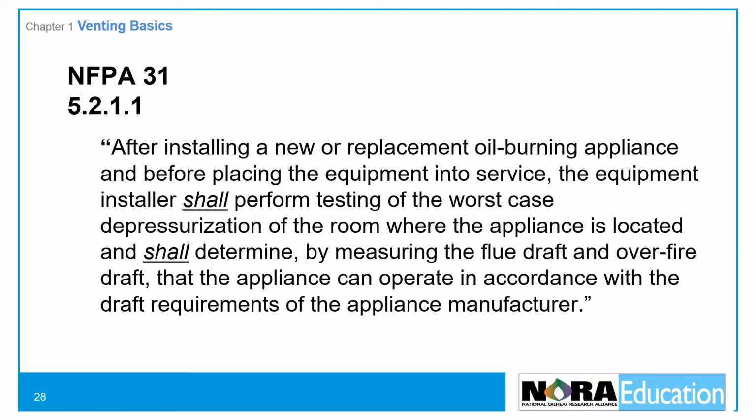NFPA 31 5.2.1 states, after installing a new or replacement oil-burning appliance and before placing the equipment into service, the equipment installer shall perform testing of the worst-case depressurization of the room where the appliance is located and shall determine by measuring the flue draft and overfire draft that the appliance can operate in accordance with the draft requirements of the appliance manufacturer.